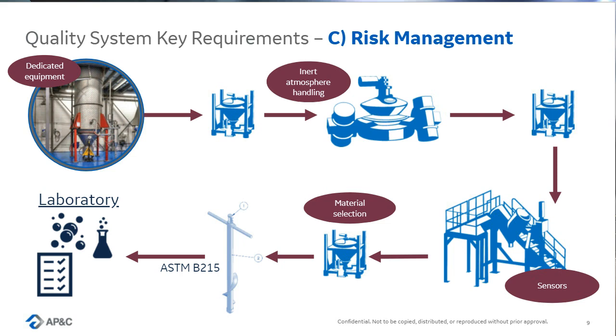But also, in all additive, one of the big risks is the fact that the powder, let's say, is kind of alive. It's easy to contaminate a powder. When we're talking about a bar in traditional manufacturing, you drop something on it, you clean it, it's done. With powder, if you drop anything in the powder, well, good luck removing it. So that's why having a real understanding of those risks and putting mitigation in place is important.